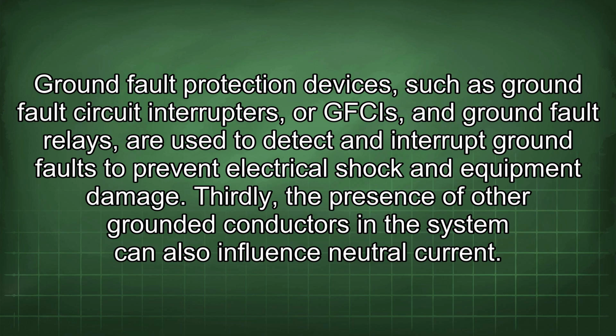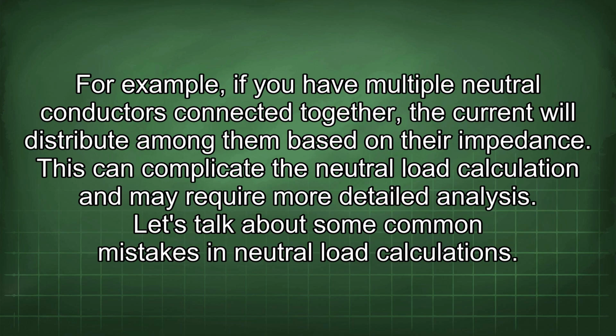Thirdly, the presence of other grounded conductors in the system can also influence neutral current. For example, if you have multiple neutral conductors connected together, the current will distribute among them based on their impedance. This can complicate the neutral load calculation and may require more detailed analysis.